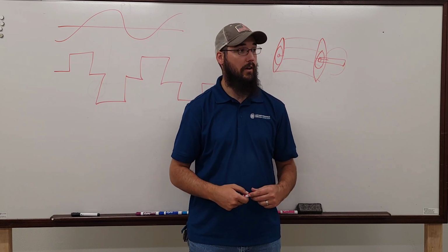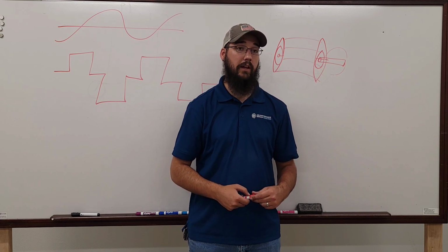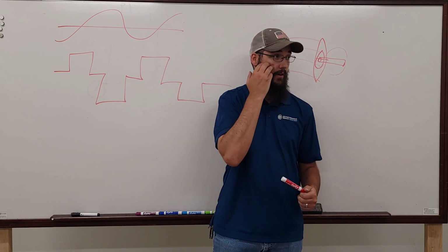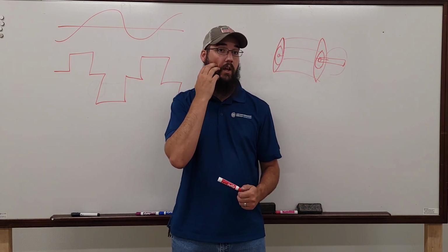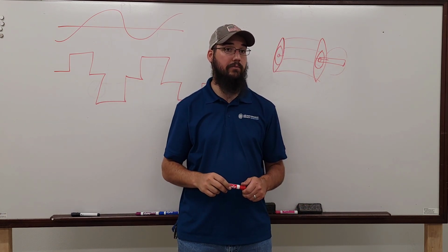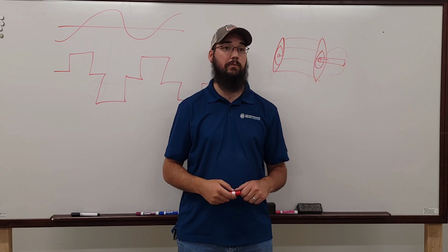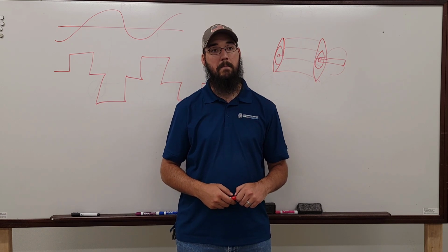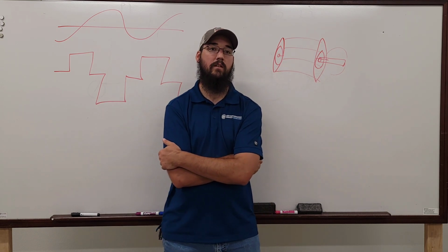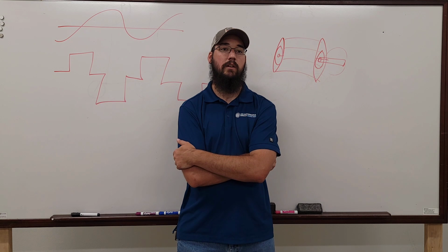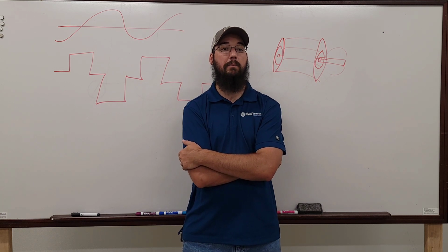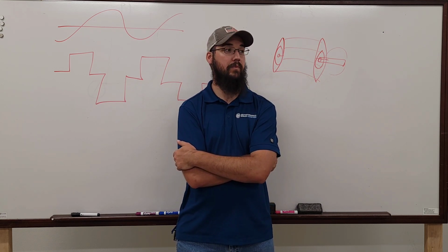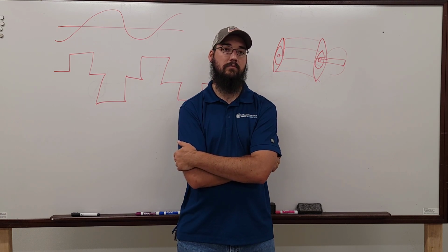I think Baldor probably has taken one of the worst hits, at least in our area. They're one of the more common ones, and they did have a reputation starting to form about them. Oh, just constant bearing issues. So what stopped it, electricity being as it is, from grounding still into the bearings? So we want to give it a path of least resistance. Yeah, I see, something more conductive. Well, we've got direct metal contact all the way through the bearing. There's just the same path of least resistance.